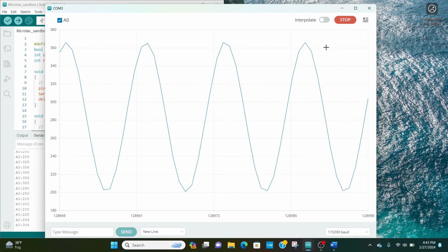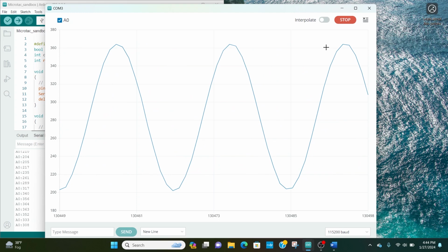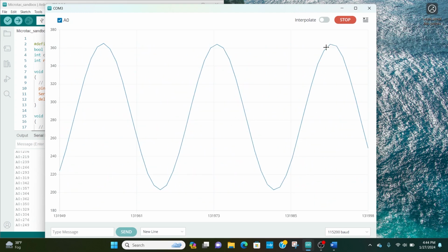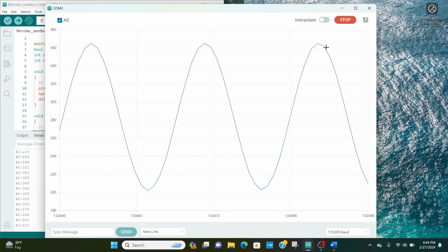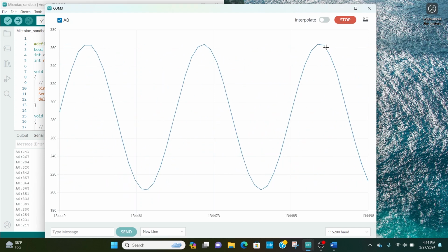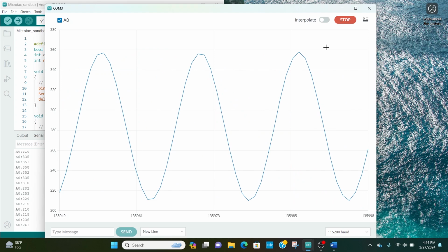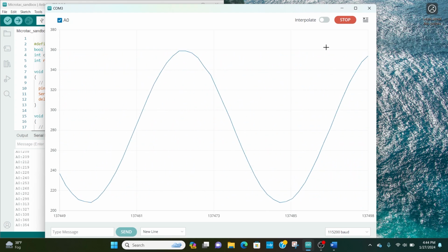Now I'm up around 8 kilohertz, and look, it's reporting that it looks like I have a sine wave at a much lower frequency. Of course, the amplitude of this has changed because my filter has knocked down the magnitude of it, but probably not enough. By the time I get up here to near 10 kilohertz, near my sample frequency, I'm really getting some bizarre behavior. So what to do about this?